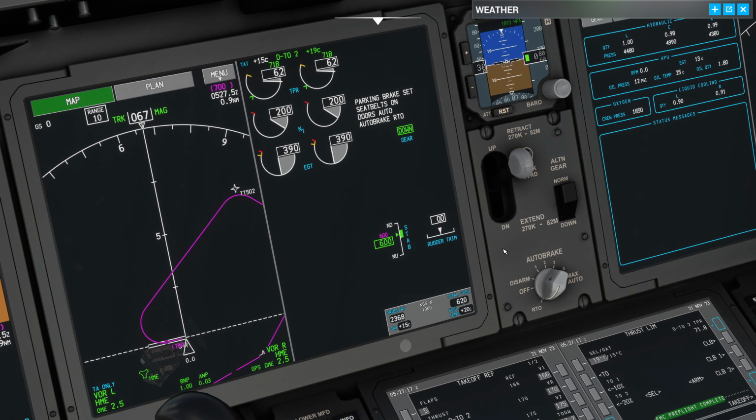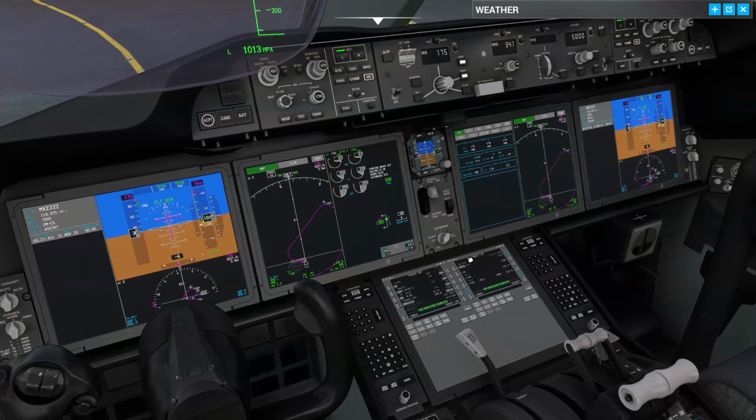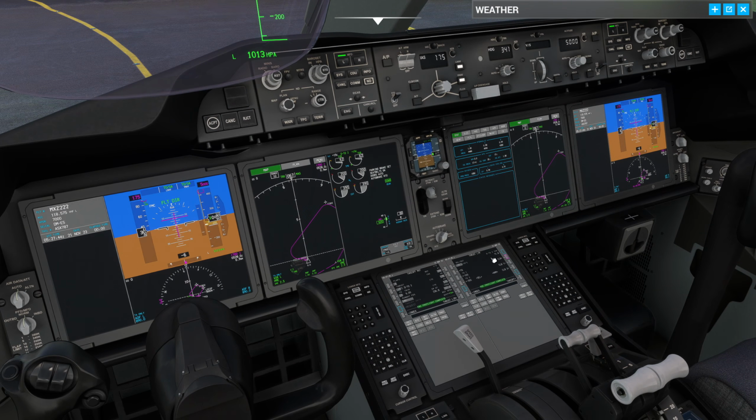There is a quirk on the real aircraft. If your trim number says 6.00, it could say like 5.5 and still draw the same green band. They're a different sort of calculation. So you might be trying to set the arrow right on the edge of this green band. If you're doing that, it's recommended that you actually go outside the green band and then trim it in towards it to prevent a nuisance caution, because it could otherwise look like it's going to be okay, and then give you a warning anyway. But there we go. So we have our trim set.